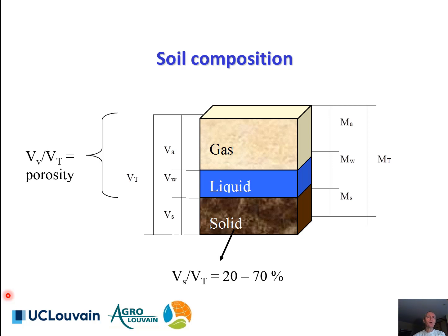We already know that soil is a porous medium, composed of solid mineral, solid liquid, and air. And we may expect that the quantity of water, air, and solid will change between the different soil types. We further may expect that the quantity of water that fills the soil pores will also change in time. We may define the quantity of the different components in a given soil volume using mass concepts, volume concepts, or a mixture of both.